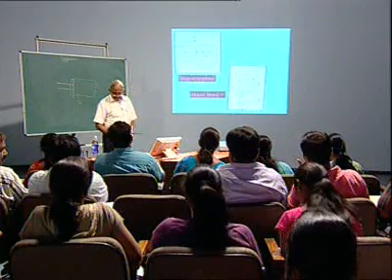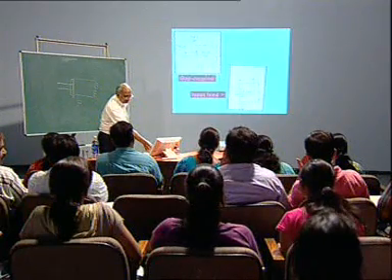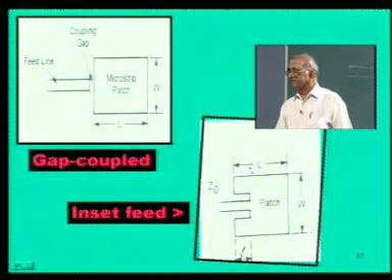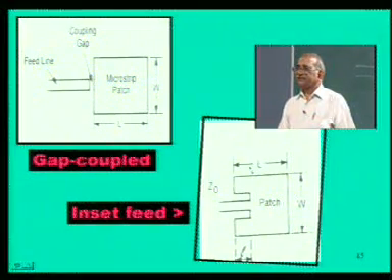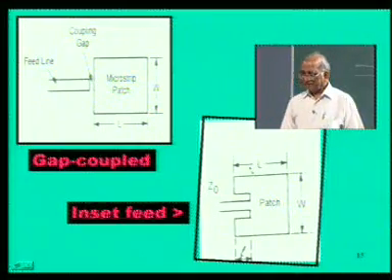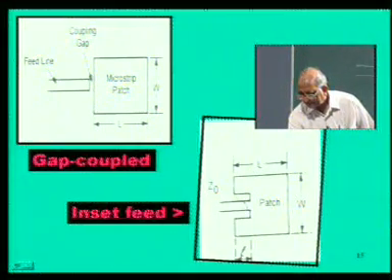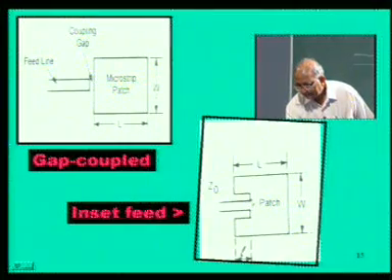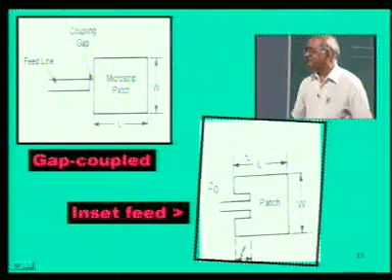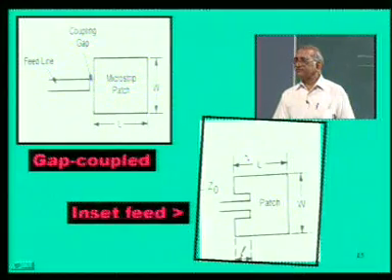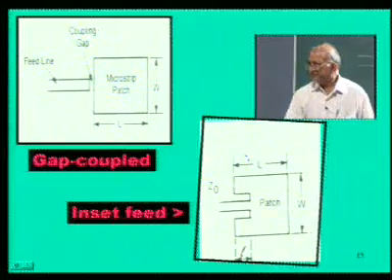Another way is that if you want to enter the feed point somewhere inside using the microstrip feed, because sometimes you do not have the choice, you have to use this feed, you can't go for coaxial feed. So, then you cut a sort of a slot, see here in this edge a slot has been cut over here, and microstrip feed goes right into inside, and this is the feed point where the input impedance is 50 ohm. This is one of the very common microstrip feed, which we call it as inset feed.